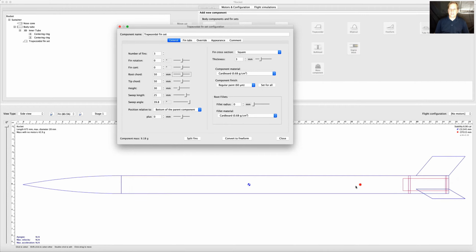And that's an important key anytime you're designing your rockets. If you're not building from a kit and you want to try something out, you can simulate it, and this will give you a really good indicator of where your center of pressure is going to be. I found this to work really well.